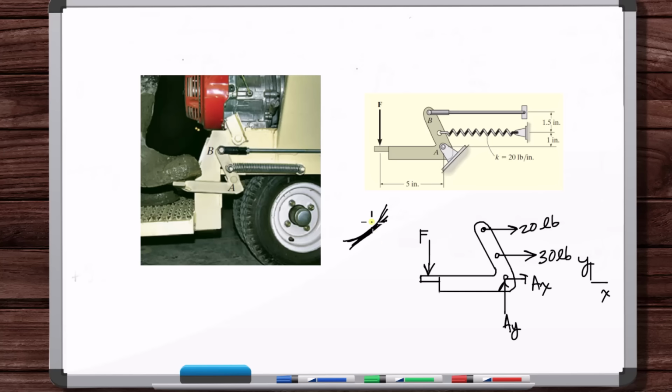Well, we will remove this. The contact force, if this is the free body diagram, will be normal to the surface. But if there is an unknown friction force, then you might have to put an unknown force with an unknown theta, an angle as well. And so then the horizontal component would be the frictional force and the vertical component would be the normal force.